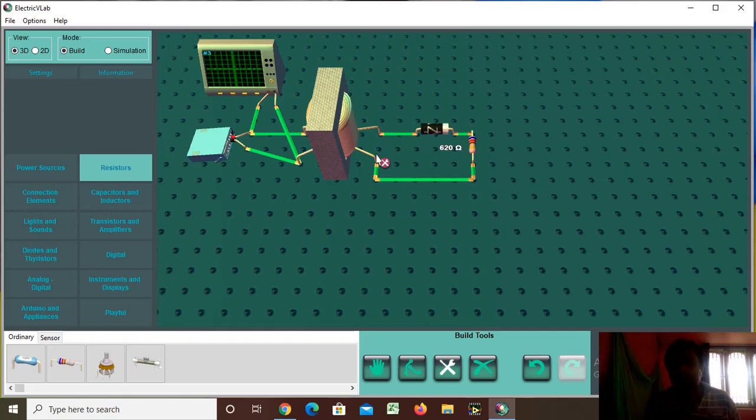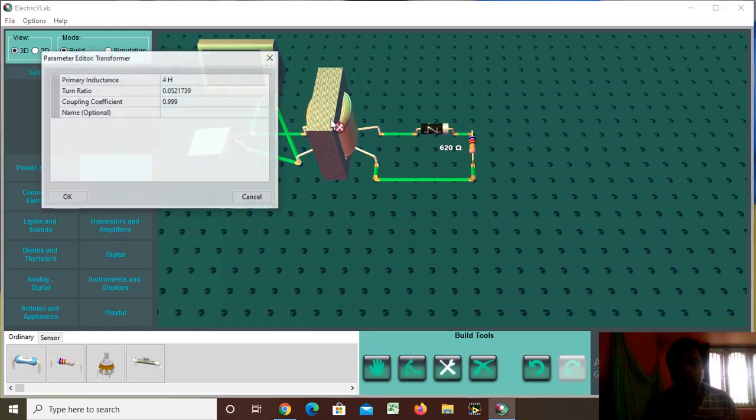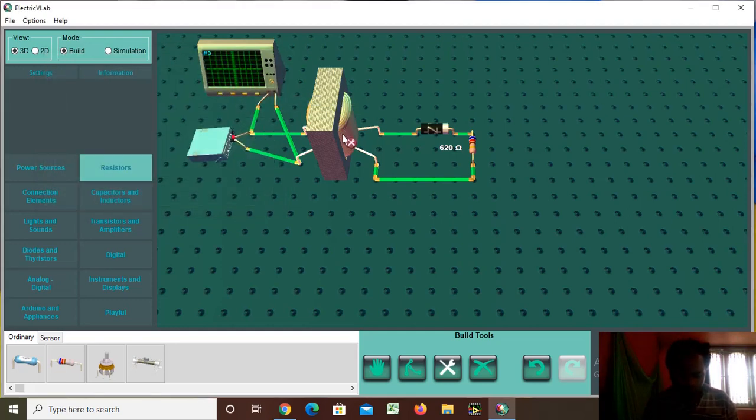I think you just remember basic electrical. You all studied transformers in electrical. So we can write V2 by V1 is equal to N, where V2 is 12. I just need 12 volts divided by 230, and you will get 0.05217. So you should put here, this is the turns ratio 0.0521739. You can change it. Suppose you want 10, then 10 divided by 230, so you will get turns ratio 0.0434. So in the secondary you will get 10 volts. That is your wish.